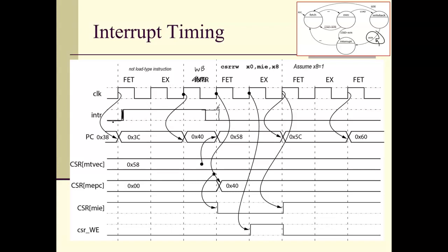So the other question, I'm going to go ahead and erase this, is the notion that, well, how fast can I turn these off? The idea is, and we'll go through this, we'll pretend this is a load type instruction. So this is going to be pretend. Okay, this is going to be 3 clock cycles. Well, this is 3 clock cycles, and then you've got an interrupt cycle. That's 1, and then for some strange reason I turn my interrupts on.